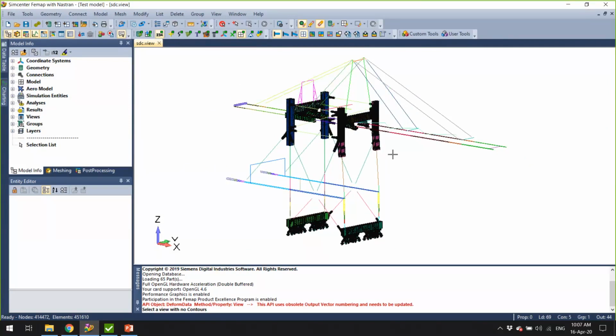As you can imagine, this kind of structure is subjected to a huge amount of repetitive loading. This model has two trolleys, on top and at the bottom. And to verify the fatigue, we need to collect a lot of data. We need to set up the loads in a certain way to be able to take into account the different working conditions and exceptional conditions of the crane, to take into account the biggest stress ranges, and to take into account the complete stress history of this structure.